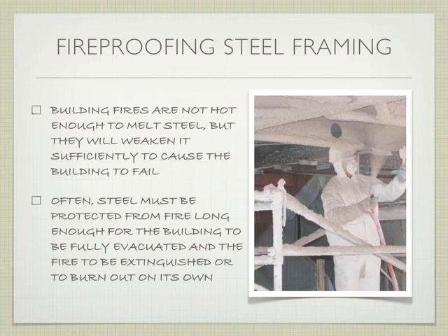And it was a progressive failure. So we'd have one little chord in that truss fail, right? Which would put more weight on either side, the trusses to either side. Both of those would then fail, right? More weight, and we've got the building that's up higher than those, pushing down on these particular trusses. So you get that progressive failure, right, due to the overheating, right, due to the weakening of the steel, and before you know it, the whole building collapses, right?